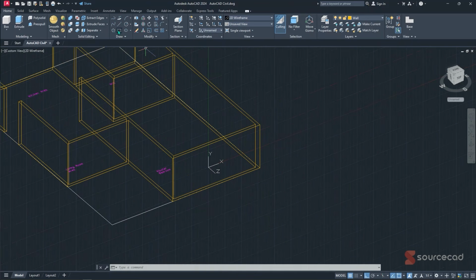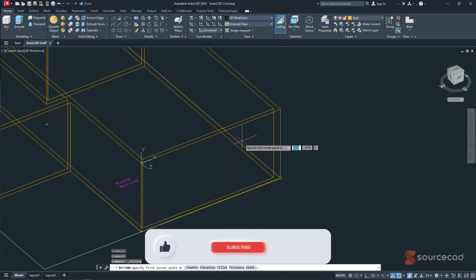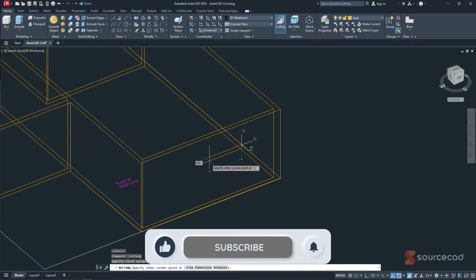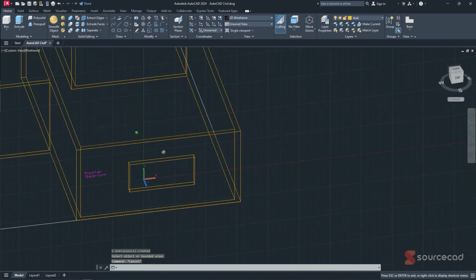And then I'll just create a very simple rectangle. So click on rectangle, and I'll draw on this face, let's say from around this point here to around that point. And then I'll press pull again. So I'll click on press pull inside here towards the inner direction, up to around there. And just like that, we have done a subtraction, and we can see a window here.